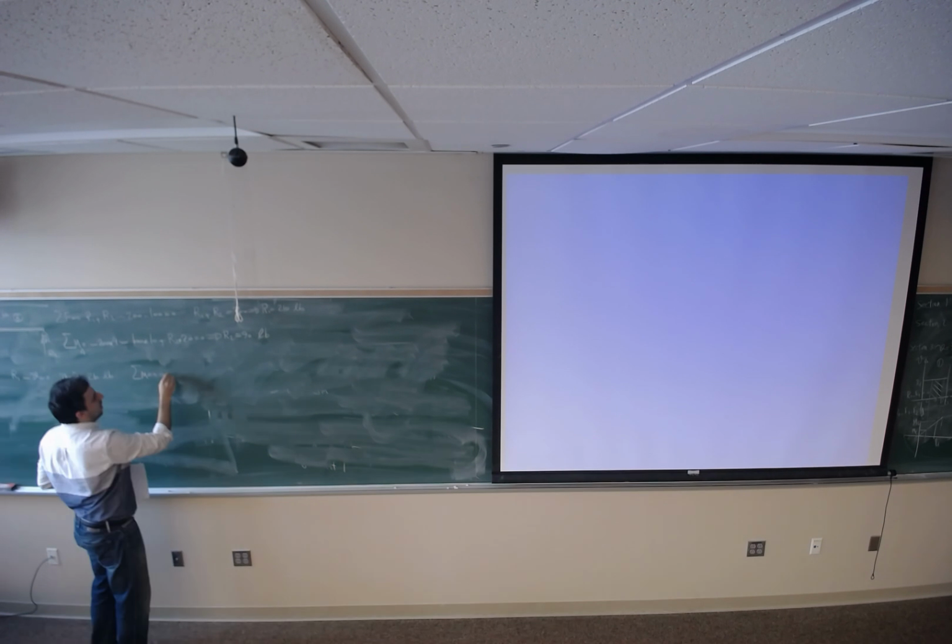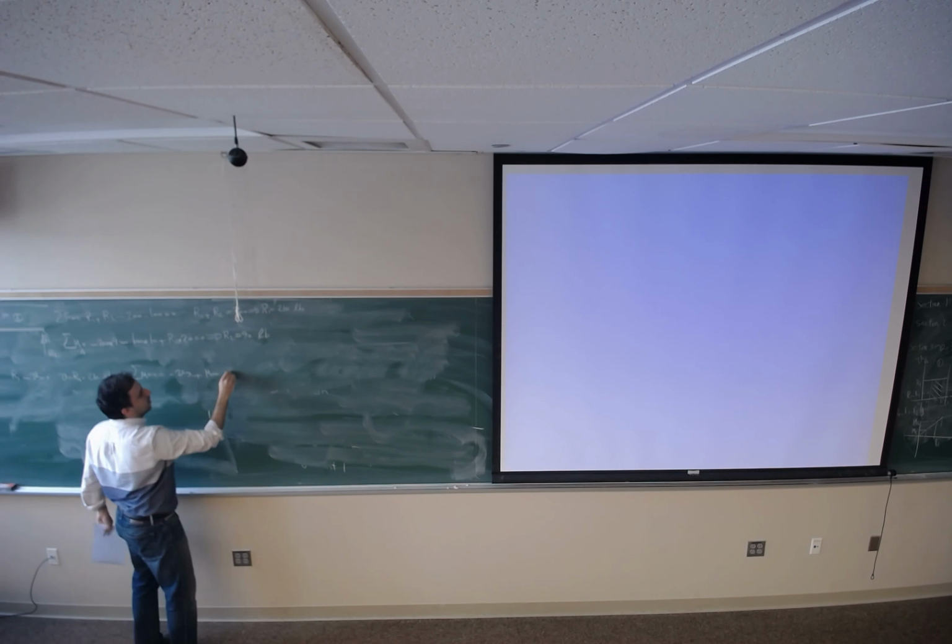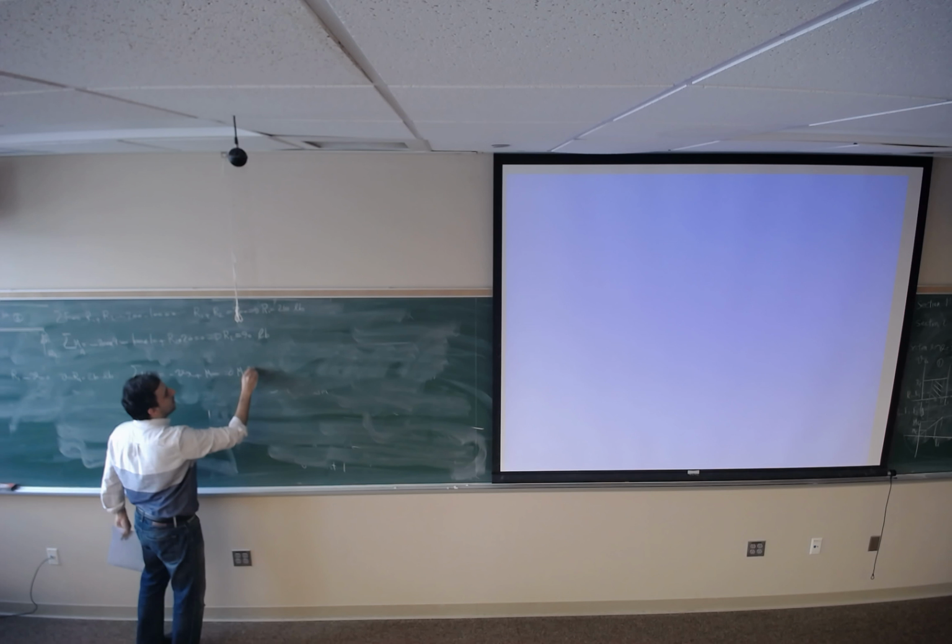This V times the distance, the distance is x, making clockwise, negative V times x plus M equals 0. Then M would be Vx, which is 210 times x. This is the bending moment for this section.